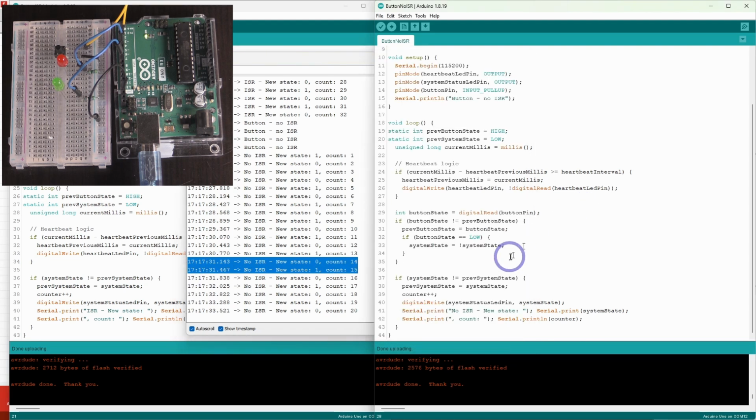So the typical way of resolving that is to basically let it settle. So when we detect that the button has gone low, just sort of let it settle for a little bit, because what happens when it's bouncing is you push the button down, but the electrical contacts sort of jump up and down due to I guess the shock of the contact, and then eventually they'll stay settled. But if you check too quickly, then you can actually detect that going up and down and then register multiple occurrences, which is what's happening when we get that repeated problem.